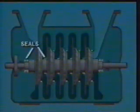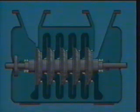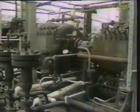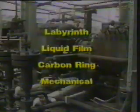Most compressors need some type of sealing to keep the compressed gas from leaking out of the compressor and to prevent leaking between stages. Particular care must be taken when the gas is combustible. That's one reason why seals are so important. Let's examine some of the types used. The most common types of seals are the labyrinth, liquid film, carbon ring, and mechanical. The simplest type of seal is a labyrinth seal.